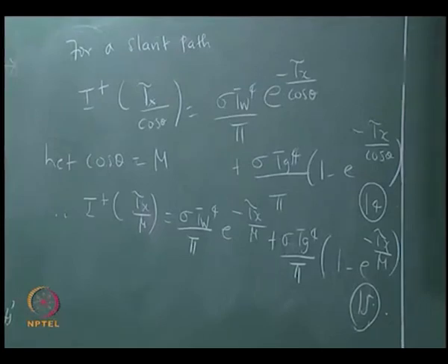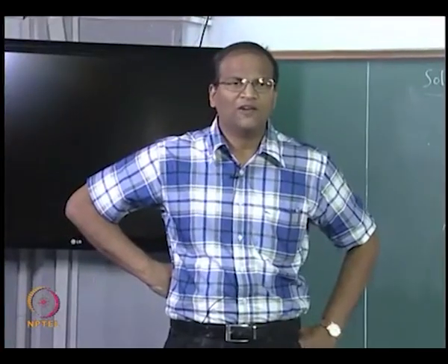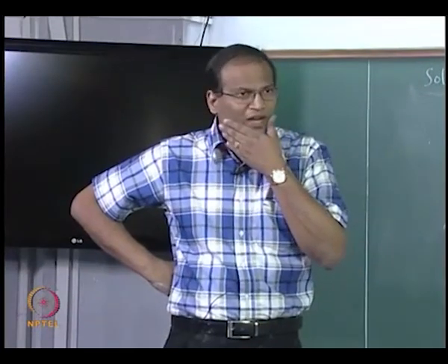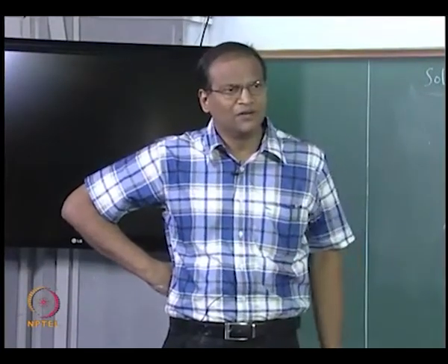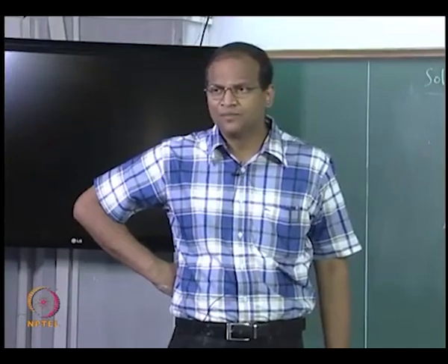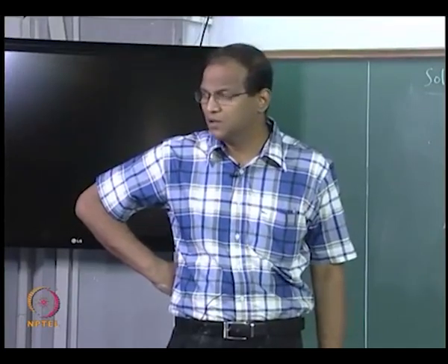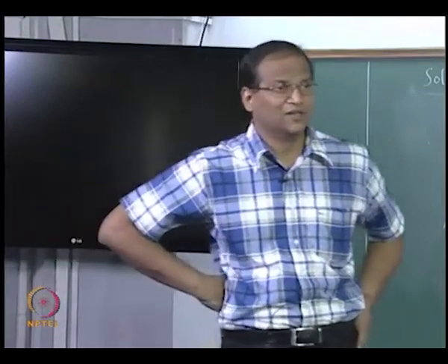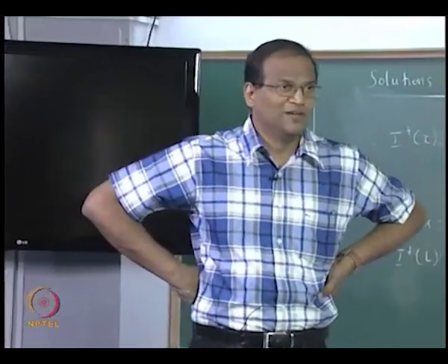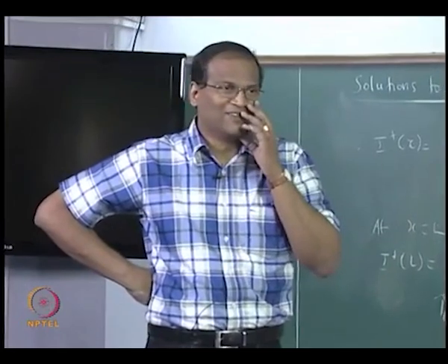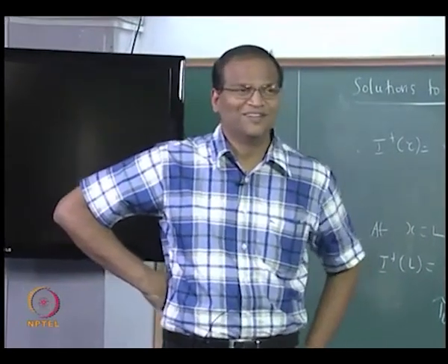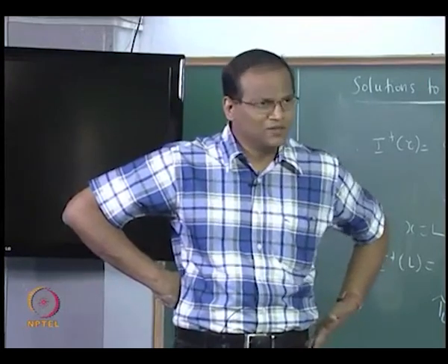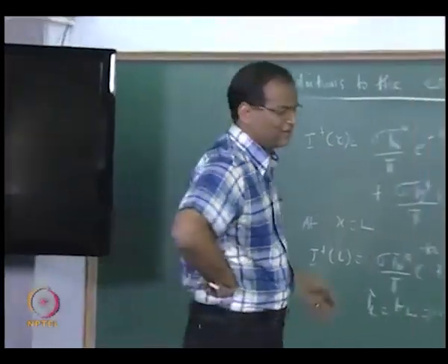Mu is very easy to handle. Normally in radiative heat transfer we use the mu. Also, did you study fin heat transfer? If you have a variable fin area, you will get the cos theta frequently. Cos theta comes frequently in several areas of radiation heat transfer. I am not sure about stress analysis and all that. Cos theta is an important fellow in many walks of life. Therefore, you treat cos theta as mu, and therefore sin theta d theta can be treated as minus d mu.